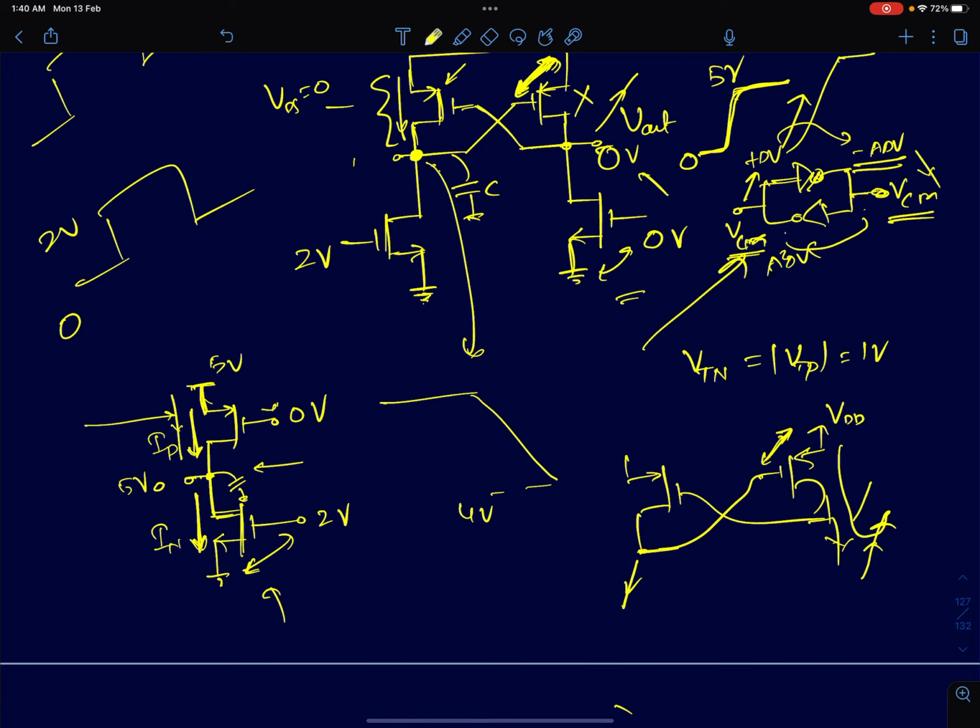As this node voltage increases, this PMOS's VGS decreases. If this PMOS's VGS is decreasing, NMOS is now more powerful to keep pulling this node to 0, because NMOS doesn't have to fight the PMOS anymore, since its VGS is decreasing. So it will keep pulling it to ground. So this node voltage keeps going further lower, now even faster.